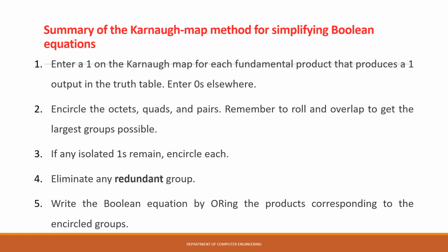In given Boolean expression, those product terms are present. We have to mark those cells by logic 1. And for missing terms, we have to mark these cells by logic 0. This is the first rule to represent given SOP expression in the K-map.